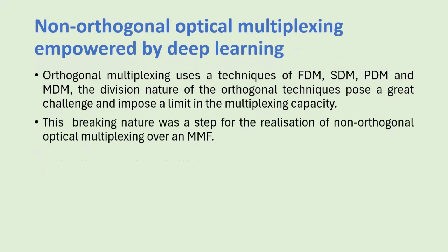Another limitation of orthogonal multiplexing is that it uses techniques of frequency division multiplexing, spatial division multiplexing, polarization division multiplexing, and mode division multiplexing. The division nature of the orthogonal techniques poses a great challenge and imposes a limit in multiplexing the channel. So this limiting nature was a step toward the realization of non-orthogonal optical multiplexing over an MMF.